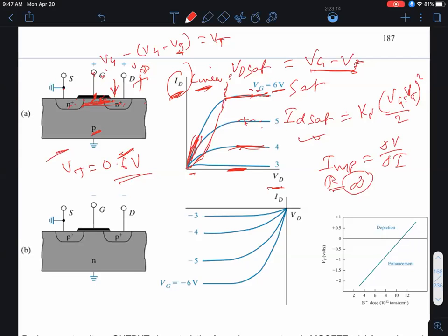So that means that if my gate voltage is 0, that's less than the VT, and then the transistor will be turned off. Okay, in this case, the gate threshold voltage is slightly below 3 volts. Okay, it's maybe, I don't know, 2.5 volts. So below that, you see that the drain current is 0. Okay, so these are known as normally off transistors. Okay, which are also known as enhancement mode devices.